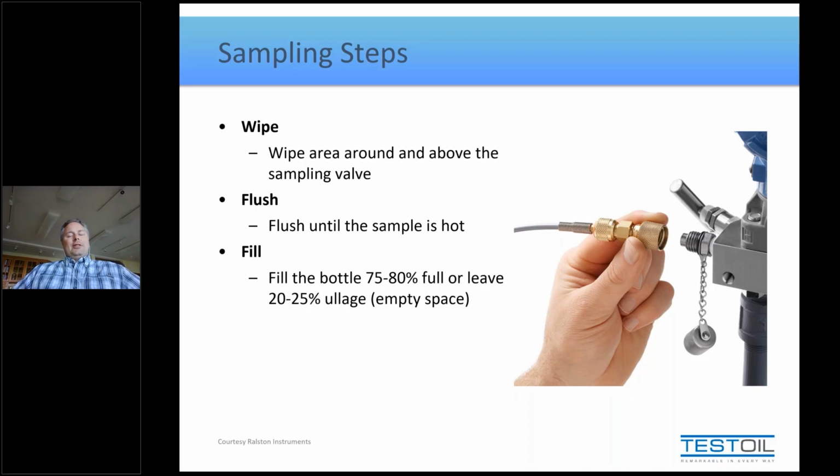Fill it. Fill the sample bottle not quite full. We recommend about 75 to 80% full. We're asking that you leave a little bit of empty space. Now, this has nothing to do with shipping, expansion, contraction, anything like that. The biggest reason we ask you to send us a bottle with a little bit of headspace is because the first step we do to any sample reaching the lab, we throw it on a mechanical shaker. And if there's no headspace in the bottle, it can't mix. We want to remix your sample so that it's as representative as the moment you took the sample, even if it's taken a couple of days in shipping to get to us.